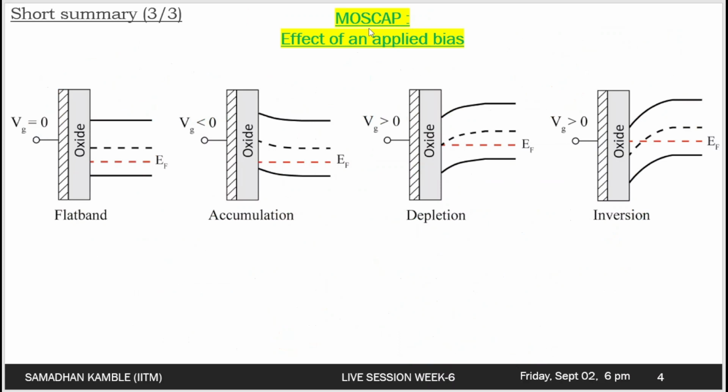So we saw that, in analogy to the parallel plate capacitor, the MOS cap can be considered a similar device, with one metal plate being replaced by the semiconductor. We also have different assumptions when we consider an ideal MOS capacitor structure, such as the metallic gate being thick enough to be considered an equipotential region. Also the oxide is a perfect insulator.